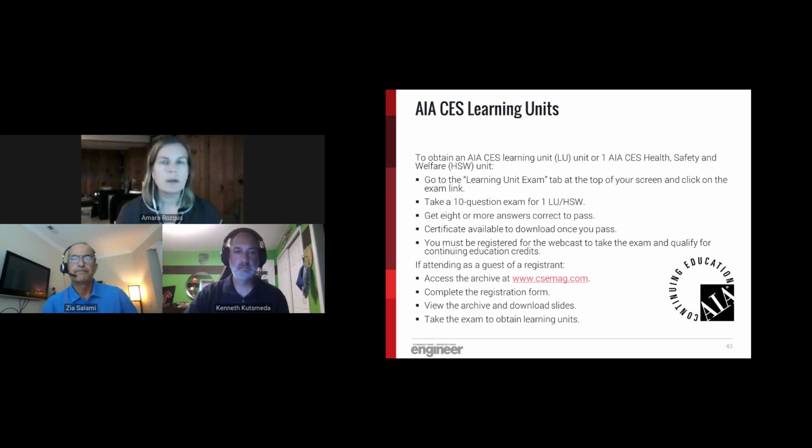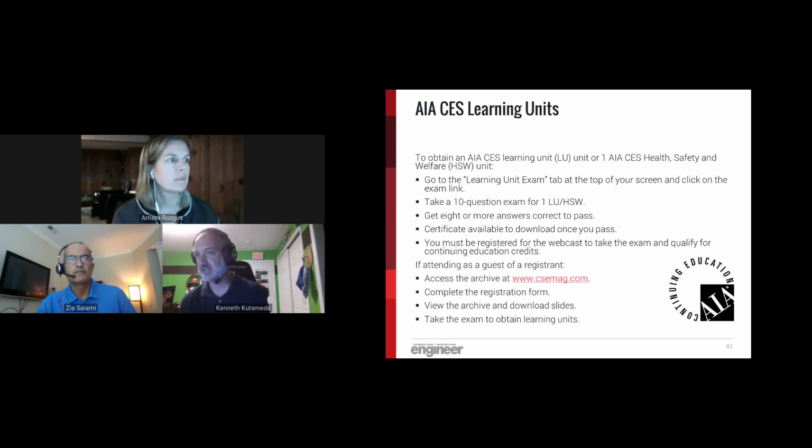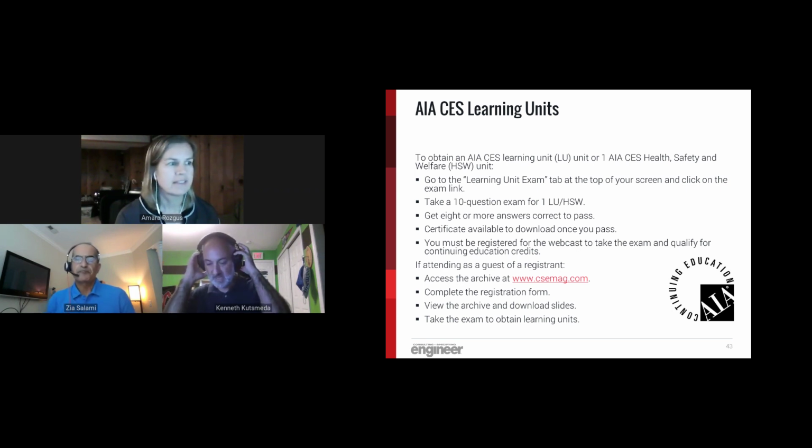Okay, Ken, this is kind of a specific question. Are infrared windows available on arc-resistant switchgear? So the answer is yes. That picture I showed in the presentation was actually infrared glass on the back of arc-resistant switchgear. The glass is almost like a bulletproof glass. It's very strong, and you can see that the encasing of the glass is welded to the frame. So it is available. It just has to be beefed up to handle that explosion and maintain it within the gear.